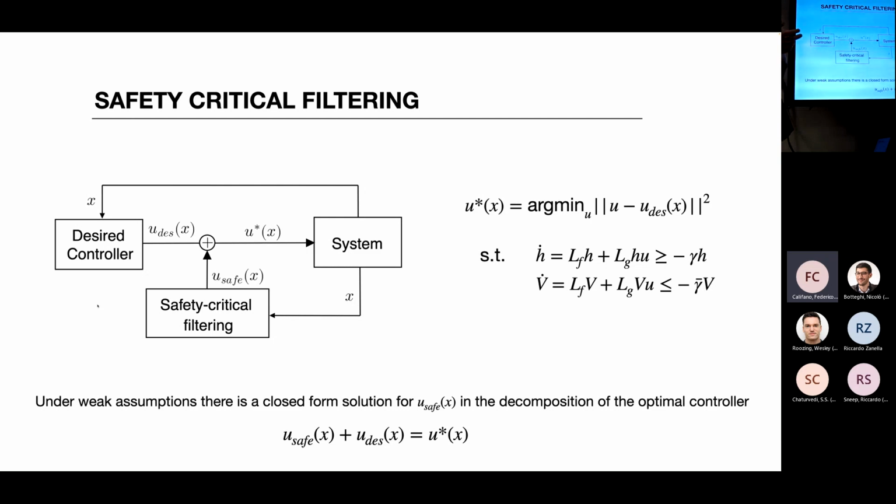It can be solved even at 1000 hertz, it's very fast. So here the idea is to use a scheme in which we have a nominal controller. Well, why should we use the CBF? I understand the stability. Say you have a nominal controller for your main task, which does stuff. The idea is using the CBF as a safety constraint.